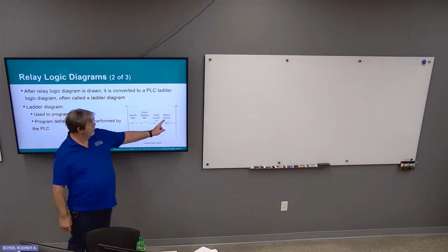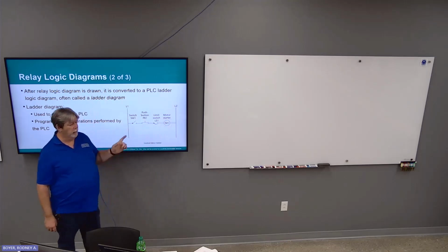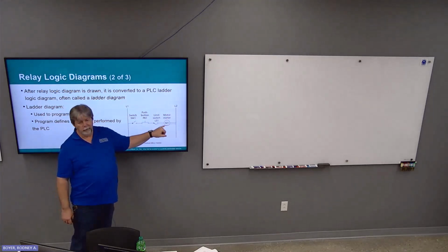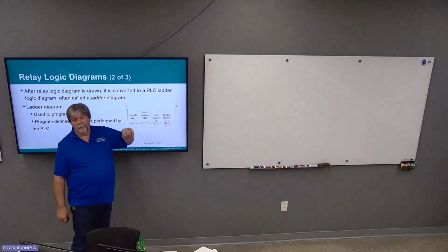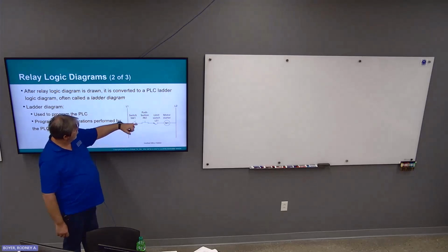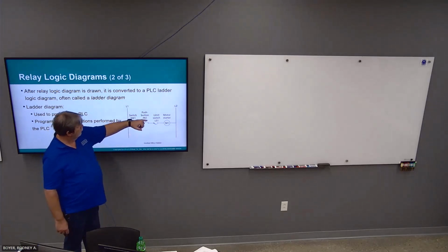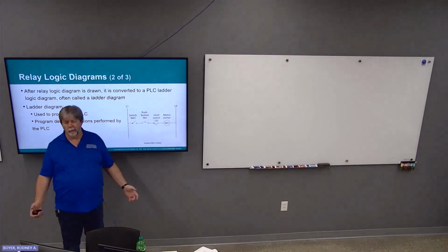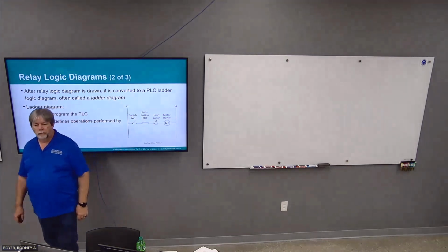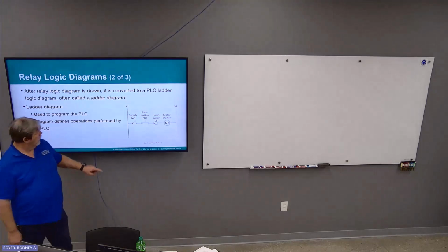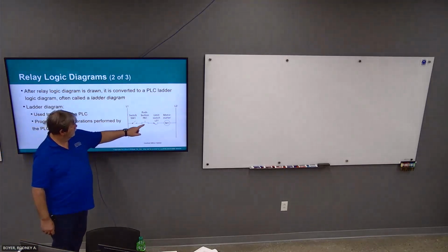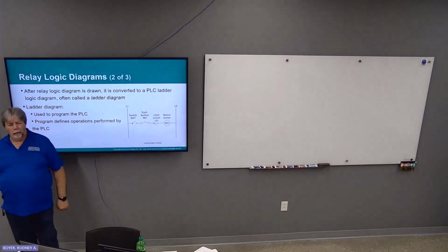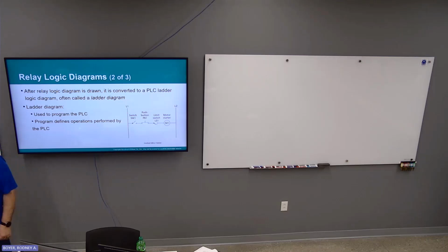In order to get this motor starter to operate, we have to have a continuous path of current to flow from L1 to L2 through this load. Okay? So switch 1 has to be closed, push button 1 has to be depressed, and then switch 1 also has to be closed in order to get the motor starter to turn on. Okay? Any break like that, any one of those open up, motor stops. Okay?